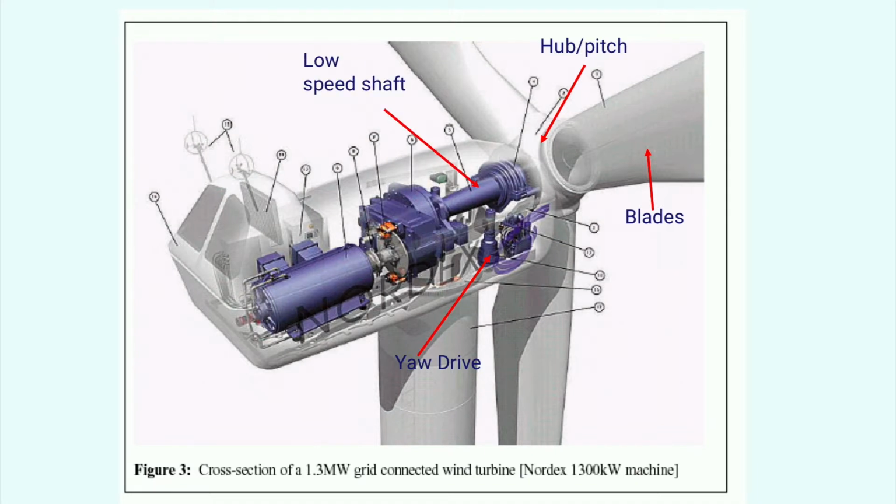The hub is connected to a large main speed shaft with a very large bearing that must withstand a large inline thrust load. During operation, this bearing also has to withstand significant off-axis loads which contribute to wear and possibly failure if these loads are excessive.